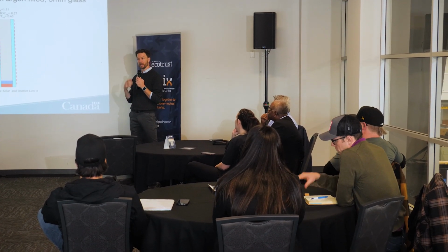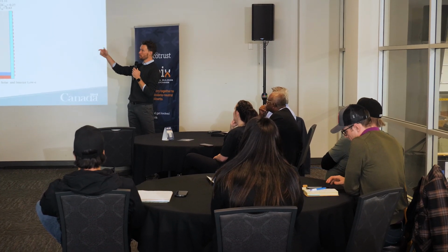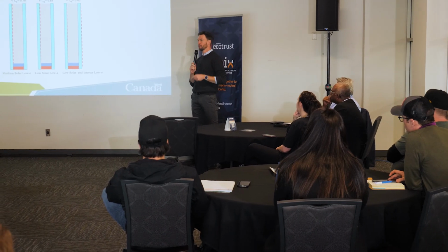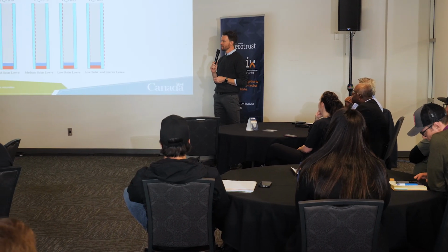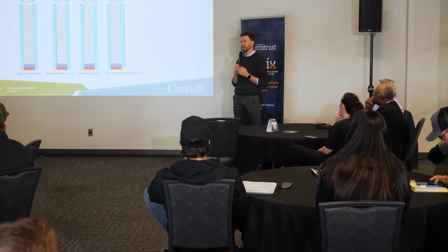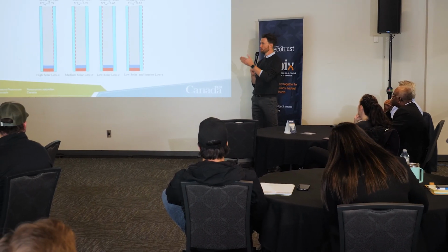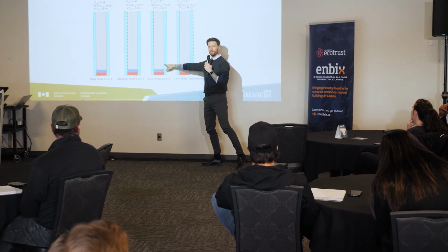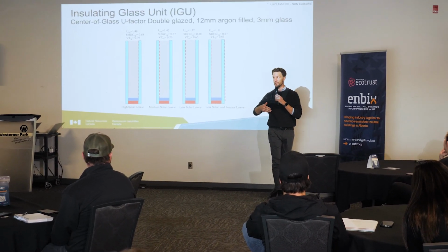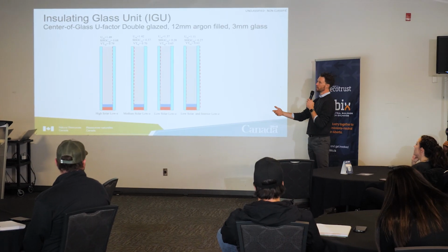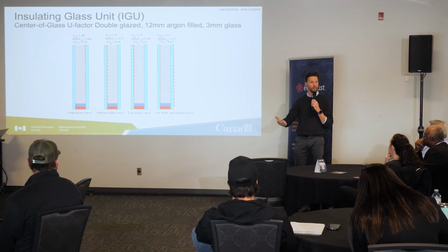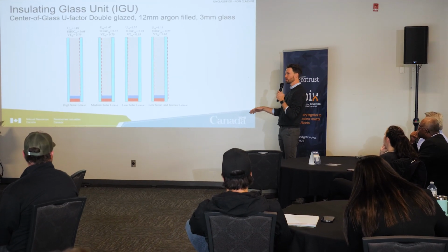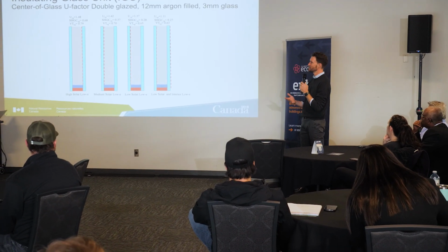But my experience has been that if you don't see those windows side by side, you could never tell. If you ask most people to look at a window and give a guess of the visible transmittance as a 0.6 or a 0.7 or a 0.8, they wouldn't know unless they see two of them side by side. So if the whole house has a 0.65, every window in every orientation, it doesn't stand out that it's lower than a 0.79 because you don't have a comparable. So don't get too nervous about those numbers going down until you get really low and it starts to get into tinted glass. That really starts to affect things.